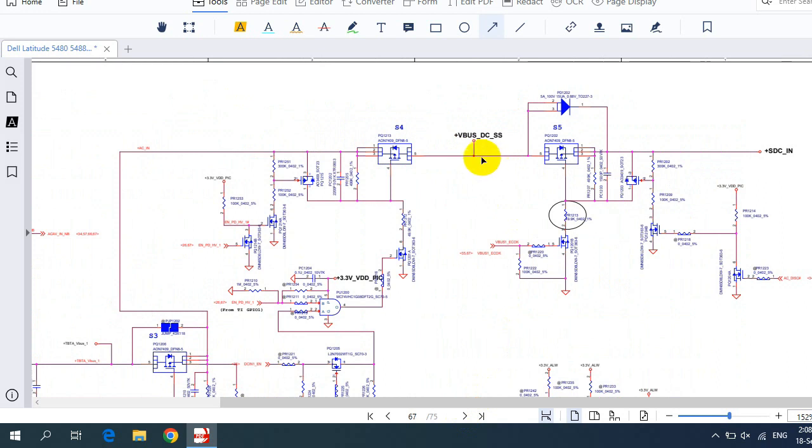So here we have another type of MOSFET. This is basically an 8-pin MOSFET. This is the most commonly used MOSFET in computer motherboards. Always the 4 pins that are connected together are the drain, and the 3 pins are the source, and over here we have the gate. But the same working principle. An 8-pin MOSFET has the same working principle in terms of testing as a 3-pin MOSFET, but its purpose is a little bit improved. So that's it, guys.